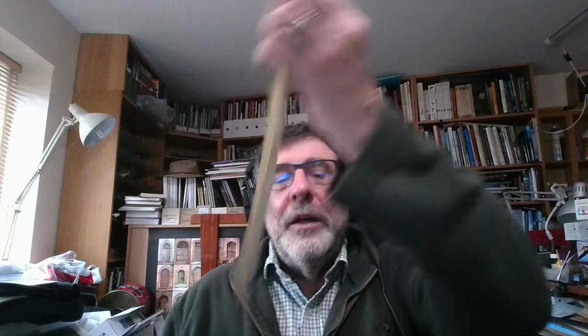Now, I've got a bit of an old fence here. It's only a slender piece of timber, and you can see it's got some end grain there, which I think in our last episode we talked about, end grain and side grain. Well, if I go along the timber and put this in somewhere along the timber, it reads here. For example, it's reading 12% there. Now that's 12%. Here it's reading 11%, so it's dry there. When I get up to the end grain, bearing in mind I only brought this in this morning, it's been out in my garden, the end grain is reading 13%.